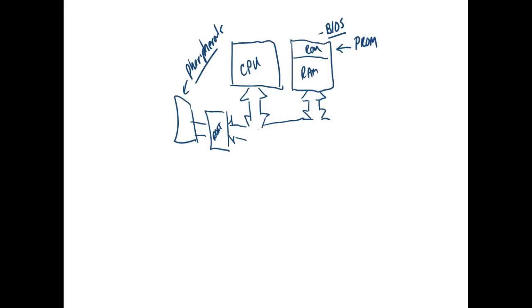So what they did, they came out with a device called a PROM. And with a PROM, it had thousands of little fusible links in there. And what we could do is we could put it in a programmer, and we call it burning a PROM. That's what we did. But the problem is, if you screwed up, what'd you do? Took it out and threw it away. Because once you blow a fuse inside a little old tiny chip, you can't get to it.